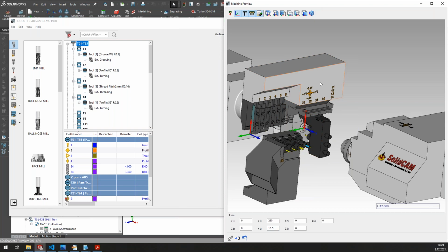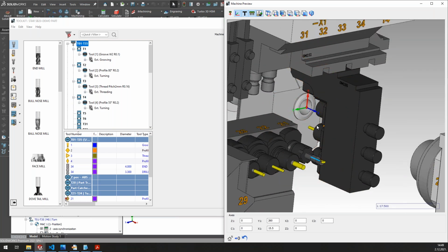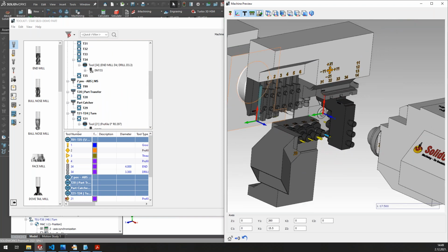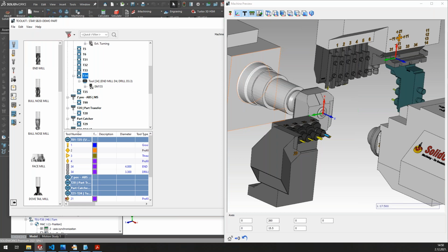Now, how this was done inside SolidCAM 2020, you had the tool station here at the tool number 34. That was a dummy tool station to mount the holder to. And then you had a station for each of the subtool items. Now in 2020, we only have one station. As you can see here, this is only one station. Now it's advanced view, but subtool items are handled with a get function.